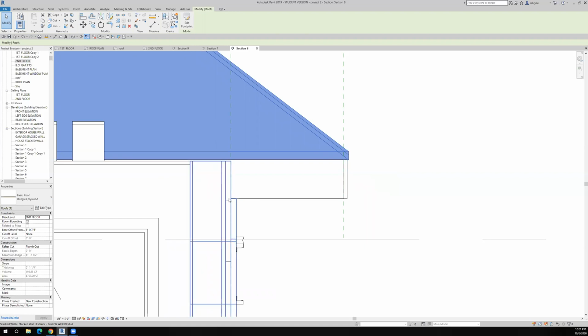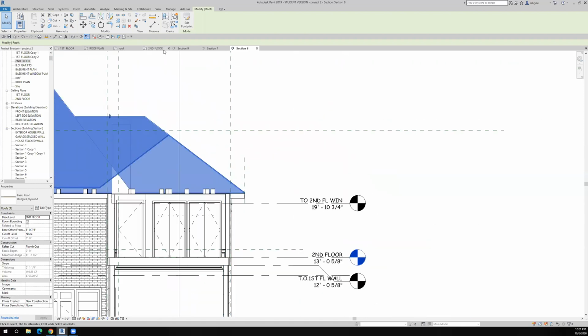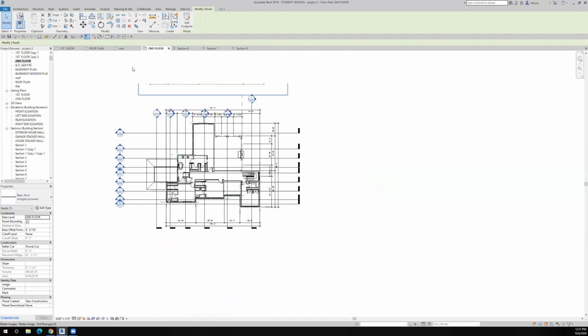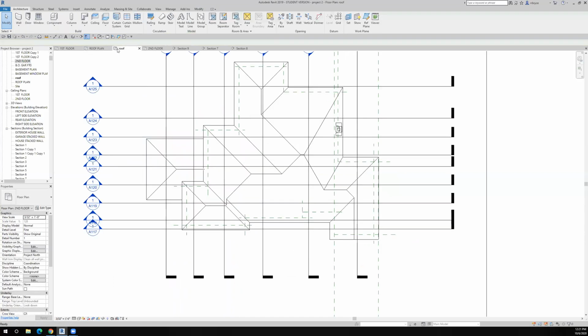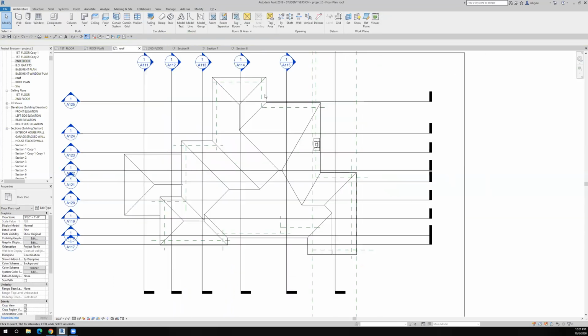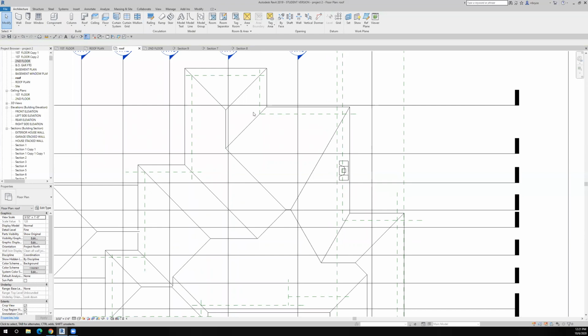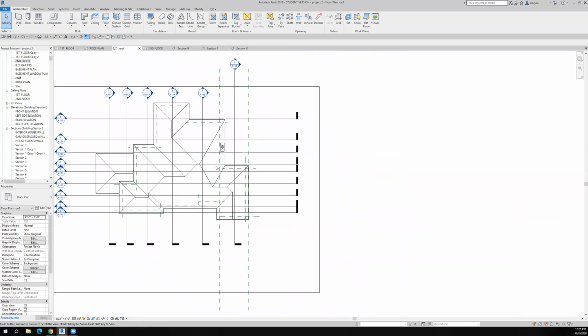And when we put it in, we'll put it in like we put in a floor. We have to provide the boundary of it. And the easiest way to know what the boundary is, is to actually put the reference planes in. So what I did was I went around the house and I put the reference planes on the inside, or the house side, of the fascia.